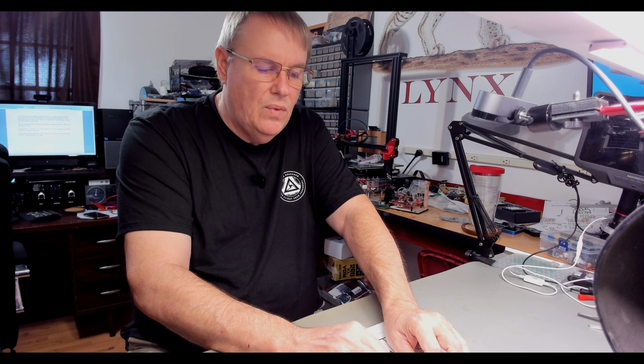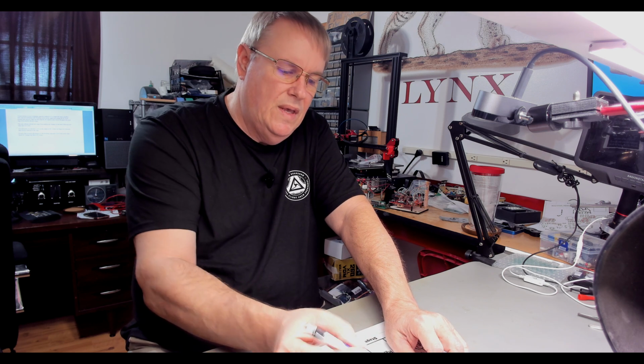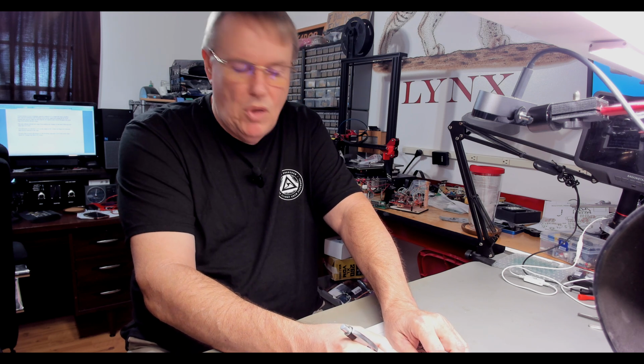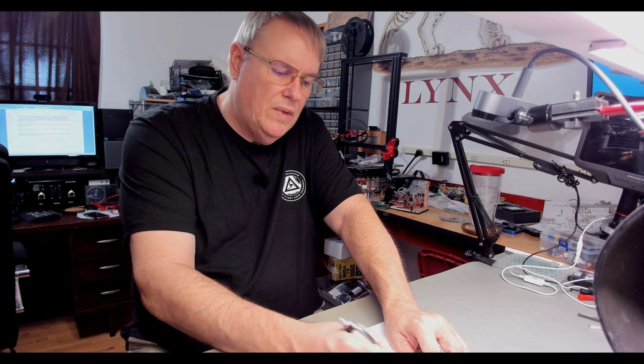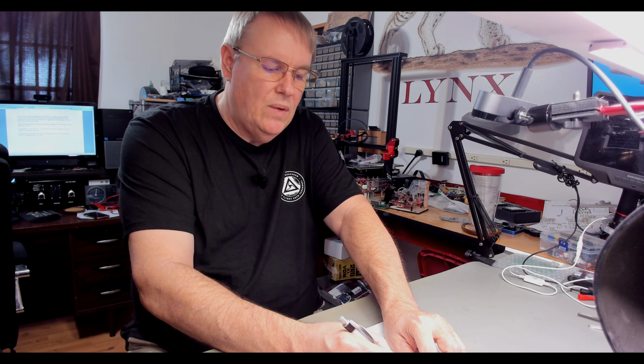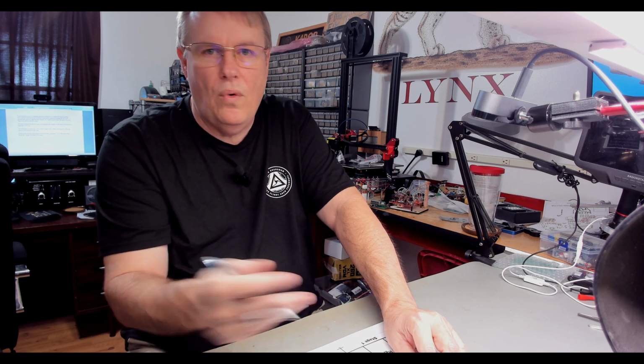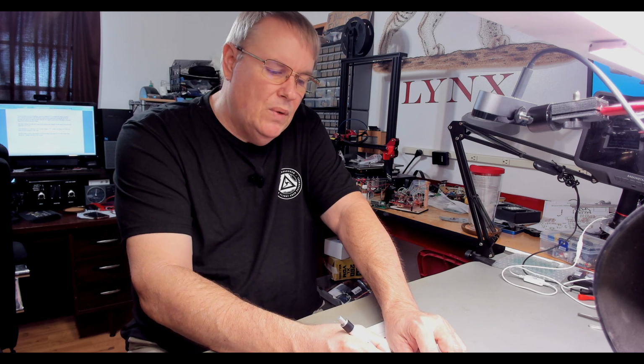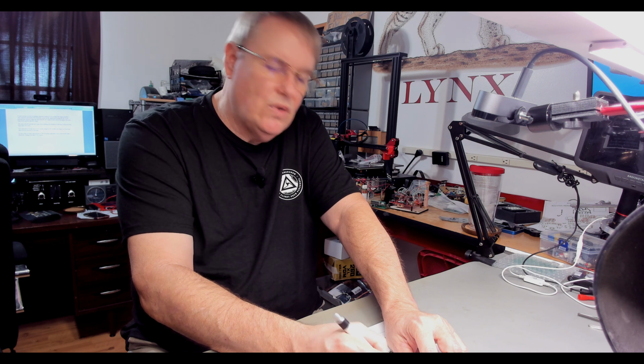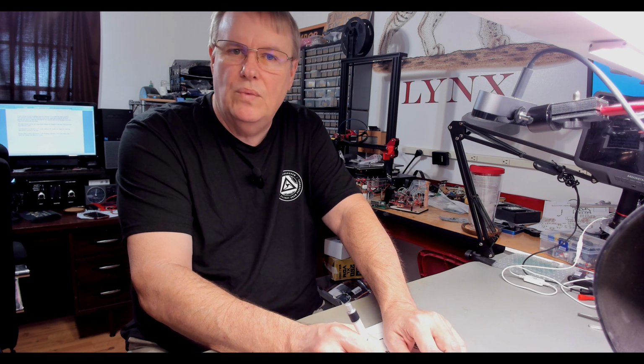I had a theory on what it was, and it turned out that the coupling capacitors or DC block capacitors, same thing, on the inputs and the outputs were the problem. And so we went in and we changed the capacitors. If you haven't seen that video, you might want to go watch that before or after this video, either one. But we went in and changed these capacitors and resolved that issue and got this thing to run within specs at the frequencies we wanted it to use.